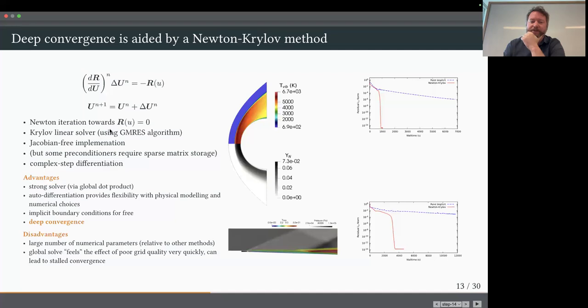Yeah, there's also two ways to answer this. The first part is that the baseline versus where you get to is not really an adjoint issue. That is a gradient-based optimization issue. So you get all the advantages of gradient-based, which is you get to use your gradient and move quickly through the design space. And the disadvantage people whinge about is that you might hit a minima, and the adjoint doesn't address that.